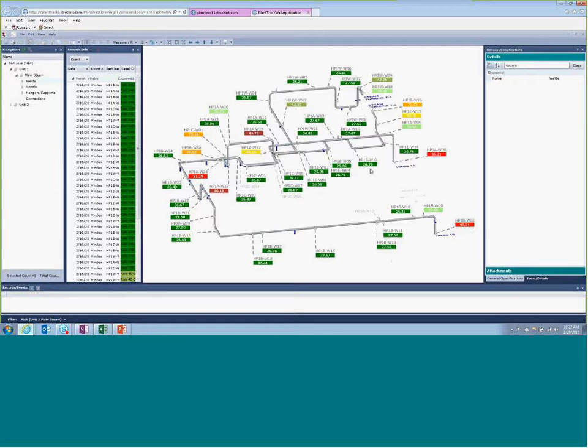So we've come through and I've worked with the plant engineer, whoever is involved in this activity. We decided, okay, we want to look at where that OLED is, look at the steam turbine connections, and then we will look at the HRSG connection. So that all captures the risk. Now, we do realize that there's an expansion loop here that we're not going to do any of at this particular inspection. So the plant has to assume some level of risk in that case, but they also have to factor in budget and all that. It would require significant scaffolding, so that's why that got pushed off. But as you can see, we're going to move forward with that particular scope.